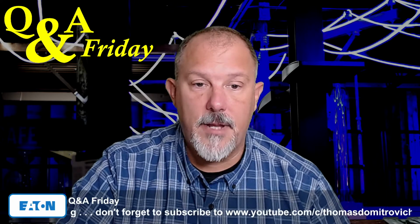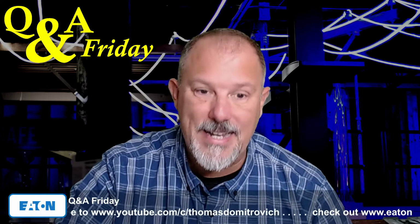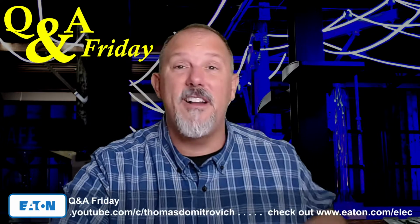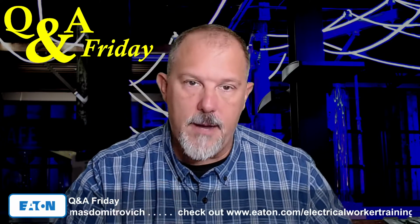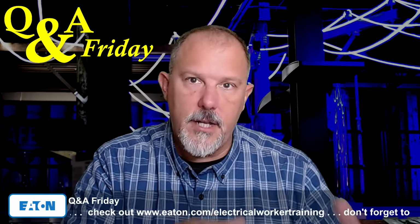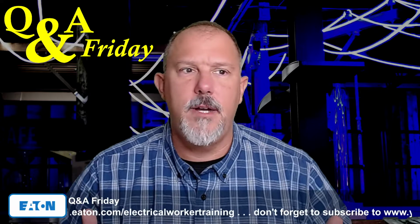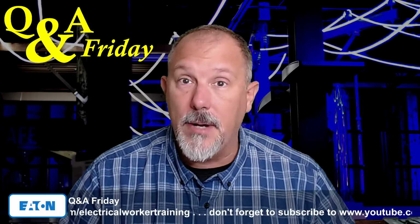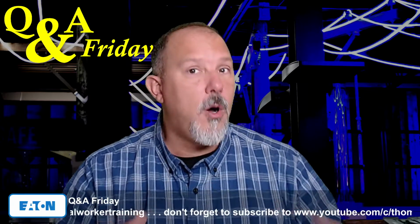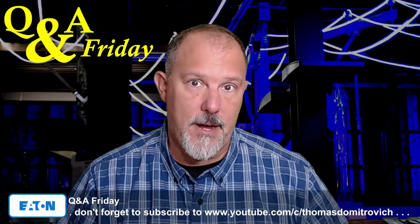It is the assembly, all breakers in the assembly, as well as the breaker in question, that have to be listed for continuous operation at 100% of its rating. That is exactly right, JW. A lot of people miss the point that if you did your calculations for 100% rated and then said, oh, I screwed up, now I'm just going to change out a breaker, you have to change them all out. And you may have to change the entire enclosure out.